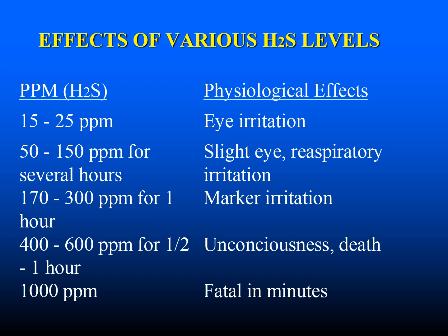At 170 to 300 parts per million for 1 hour, they'll have marked irritation. 400 to 600 parts per million for a half hour to 1 hour will cause unconsciousness and lead to death. And at 1,000 parts per million, it becomes fatal in minutes.